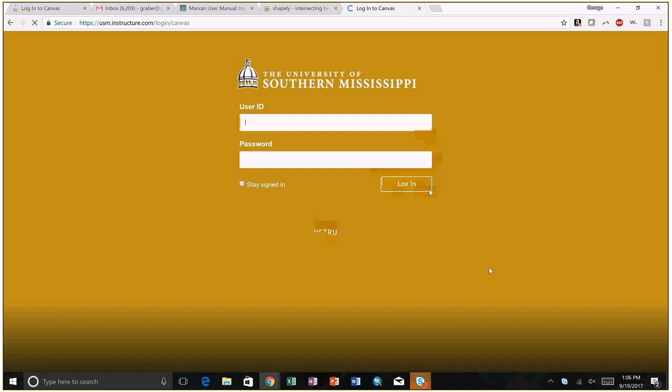So all you're going to do, whether you're at Gulf Park or Hattiesburg, is put them in a table with the location, the easting, and the northing. The reason why I put them like this is the easting is the X, the northing is the Y. Sometimes the N will be reported first, like in some GPS apps, the northing is reported first, but make sure you put it in